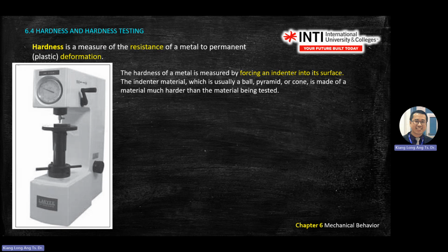So with a pyramid shape, when you do indentation, what do you see after you indent it? It's like a chop. So what do you see from the top? You see a square or diamond shape like that, right? But there's a depth inside there. If you draw it in 3D, there's a depth.